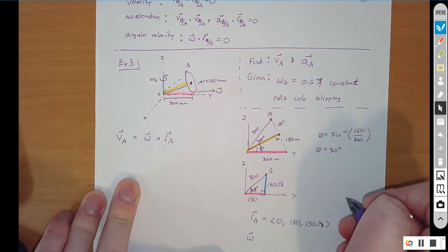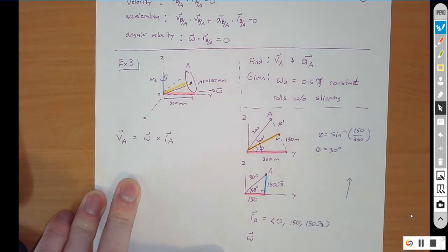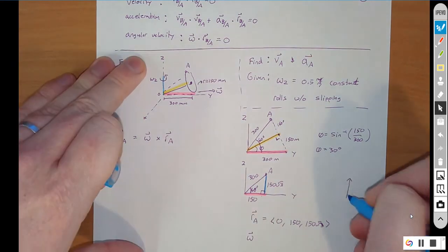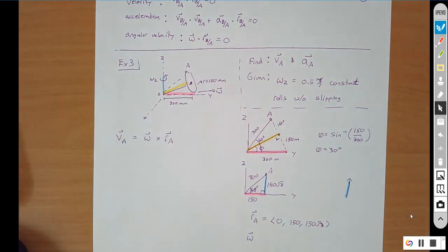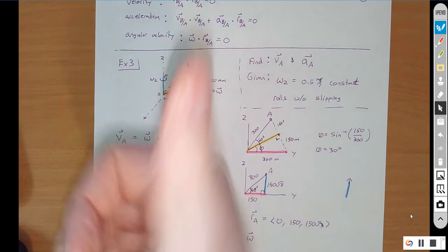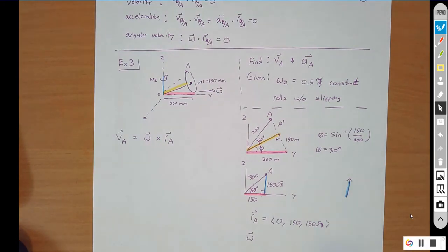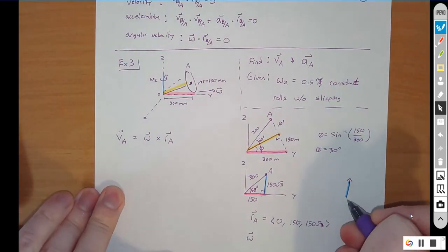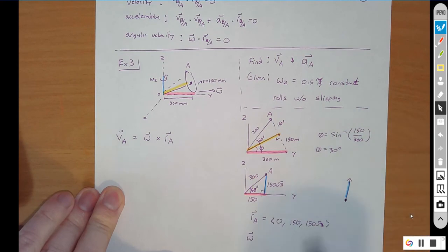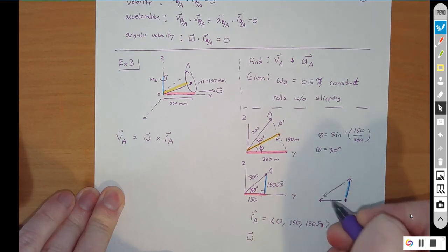Basically, I'm going to have my z go up. Why up? I know that it rotates positive about that z-axis. Using the right-hand rule, its axis of rotation points up, which means it starts here. So this pink vector also has to start here, which means that if I'm going to do vector math, I need to make it go this way, and then come down so that I end at the same point.